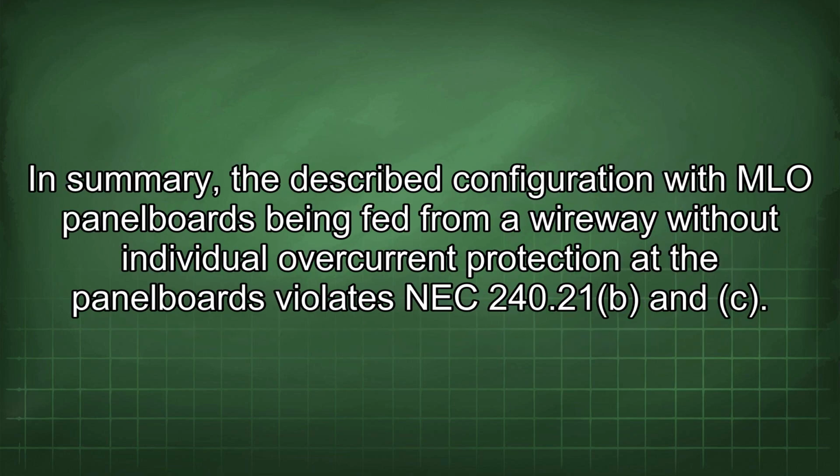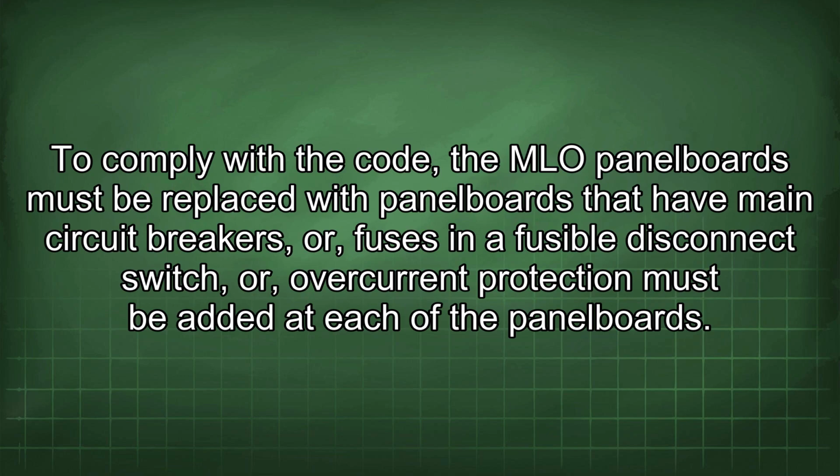In summary, the described configuration with MLO panelboards being fed from a wireway without individual overcurrent protection at the panelboards violates NEC 240.21(B) and (C). To comply with the code, the MLO panelboards must be replaced with panelboards that have main circuit breakers, or fuses and a fusible disconnect switch, or overcurrent protection must be added at each of the panelboards.